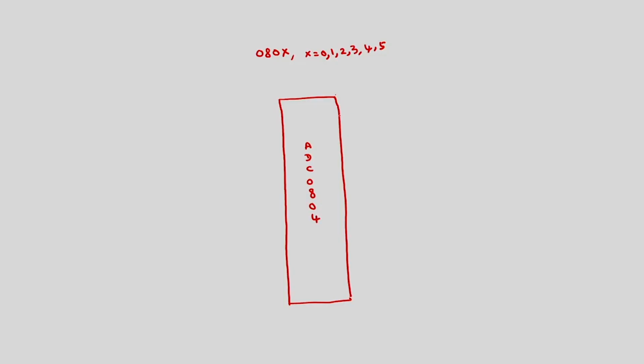Okay, so the different signals are, we have a data bus, because this is an 8-bit A to D converter. So, input is analog value, output will be digital value, this is 8 bit, D7 to D0, the 8 bit digital output. And you should have some analog signal. We have two analog signals, one is called V in plus, another is called V in minus.